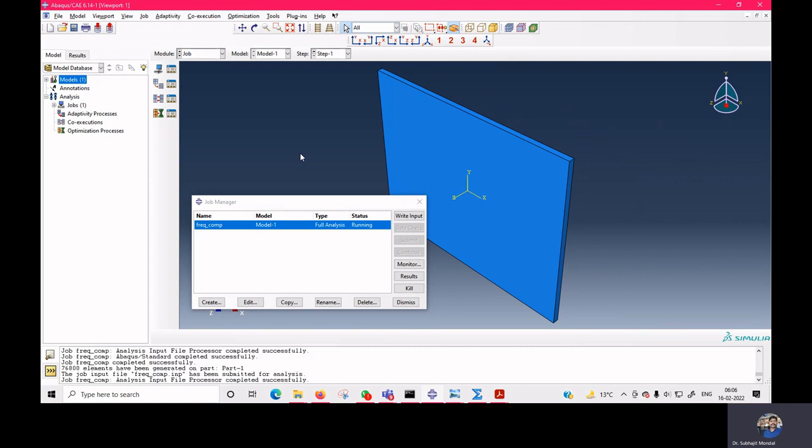Here you can see it is taking more time. If you increase the number of elements, then your degrees of freedom will also increase, and your K matrix will also increase. So here we have root under K by M, so the mass matrix will also increase. So again there is involvement of the inverse of the mass matrix. If the degrees of freedom increase, it will take a long time to get the inverse, and a long time to get the result also.